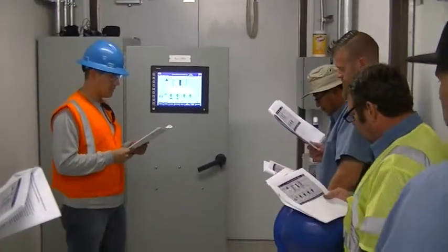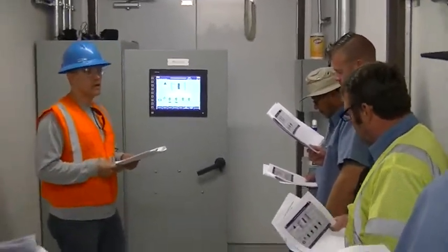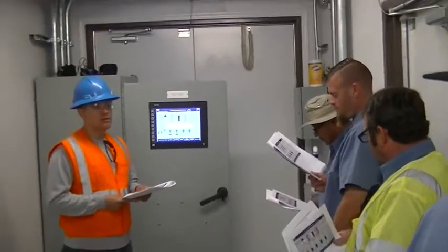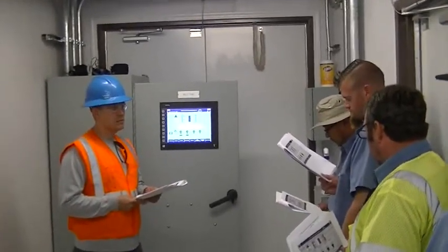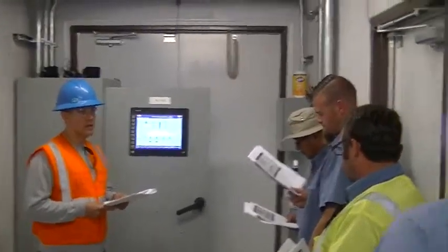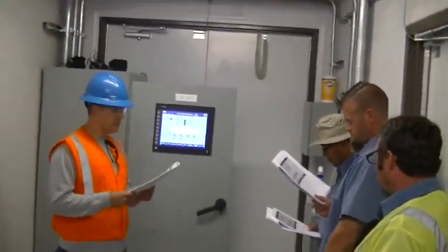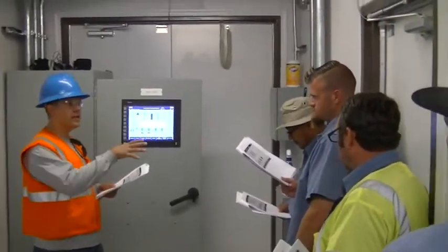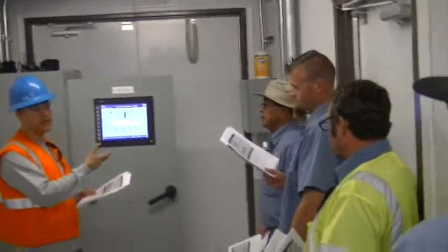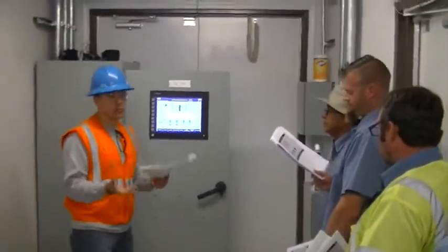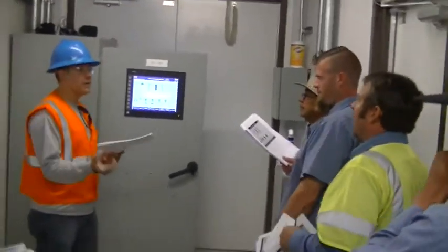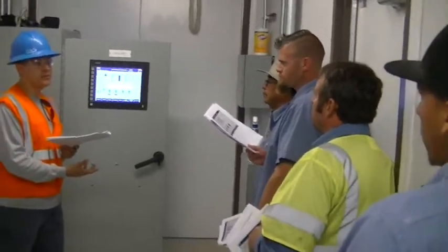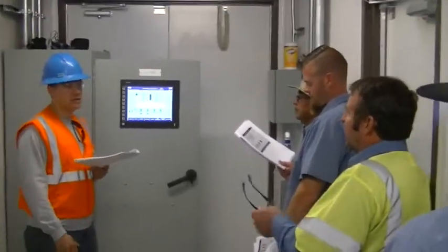So any idea what would cause a low flow? Would it be a problem with the pump? It could be caused, yeah, basically that low flow is saying you're not getting a flow signal through there. In other words, your pump is running, but there is no gallons per minute going through. Right, like under 200 gallons a minute or something.